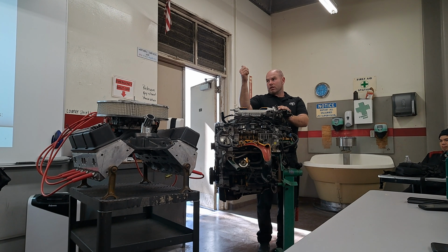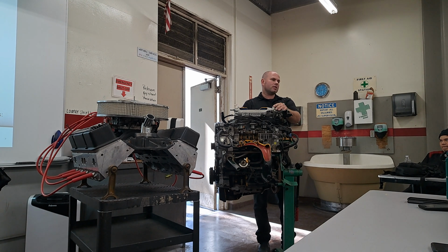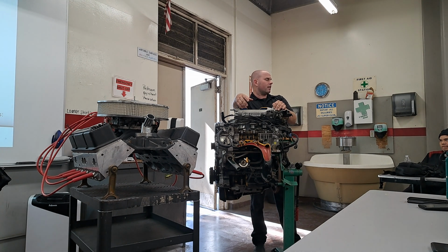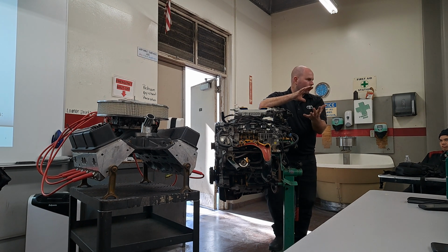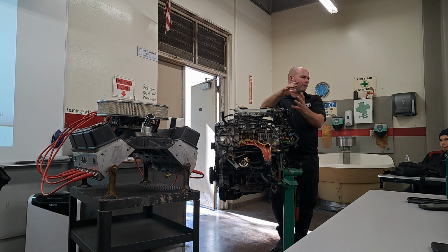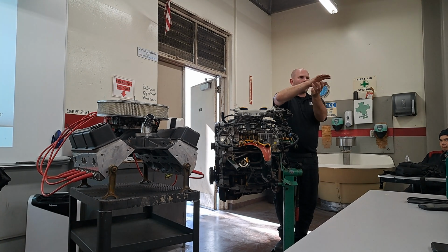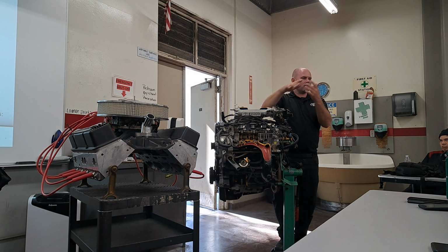I've got to tell you, one of the things that we discuss on here is the head gasket. The head gasket has a pretty tough job. It's got to withstand the combustion pressures. It's got to contain coolant. It's got to contain oil. But additionally, the iron is going to heat and cool at one rate, and the aluminum is going to heat and cool at a different rate. So they're moving separate from each other. So the head gasket's got to be okay with the head maybe sliding across it a little bit and having some movement in there. It's pretty tricky.